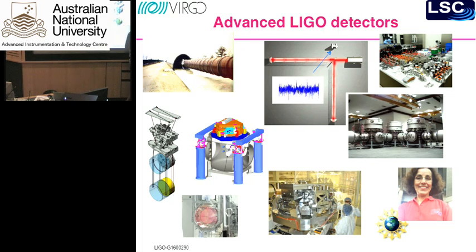Imagine this is upside down. This is a 6-axis isolation stage, and this one is all active. So the pendulum has 4 stages of passive isolation, and this one has 6 axes of active isolation using seismometers and geophones to keep the platform inertial. And then this whole thing is attached to another one of these, like that, and then it's upside down, and that's what you see here.